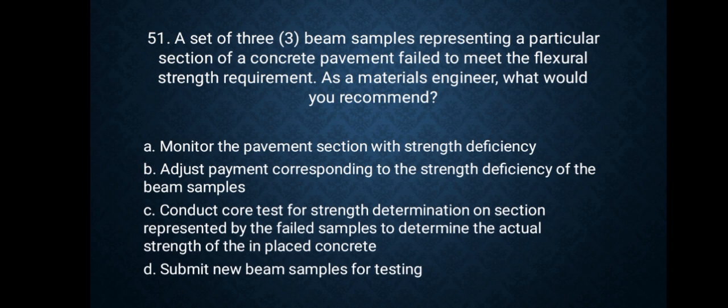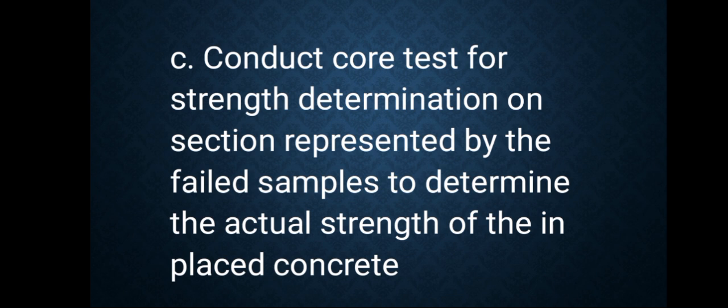Number 51. A set of 3 beam samples representing a particular section of a concrete pavement failed to meet the flexural strength requirement. As a materials engineer, what would you recommend? You have chosen from the choices. So, the answer of that is C. Conduct core test for strength determination on the section represented by the failed samples to determine the actual strength of